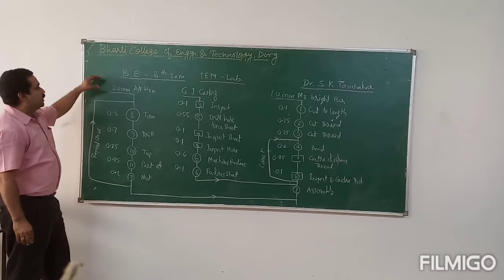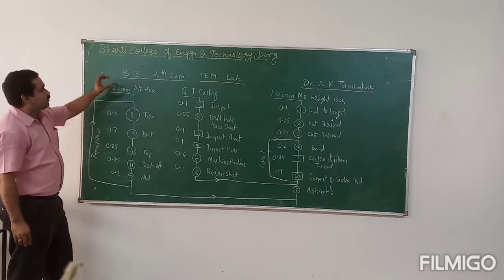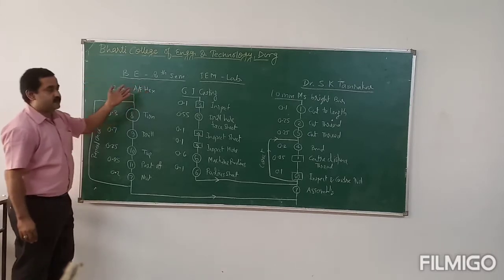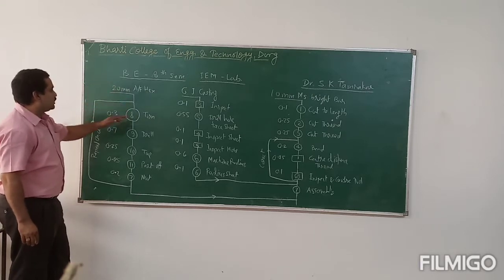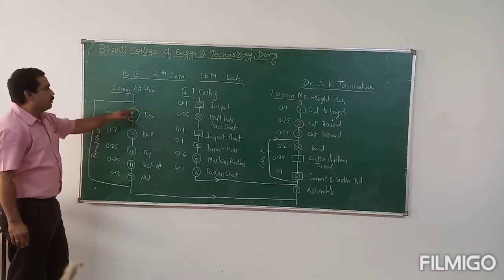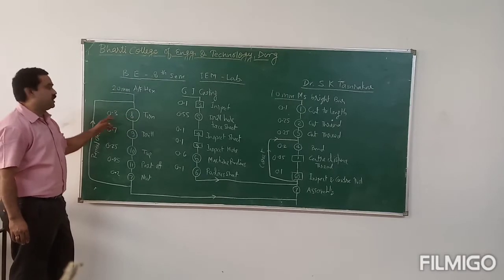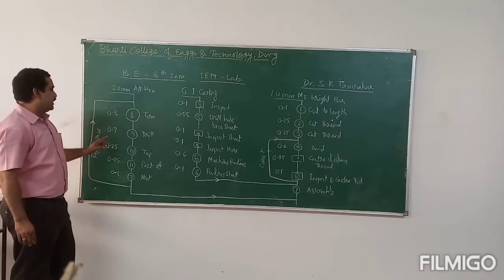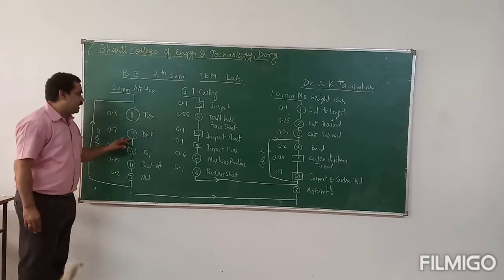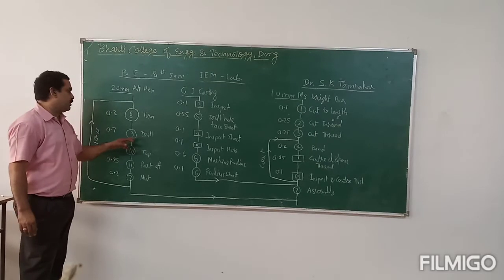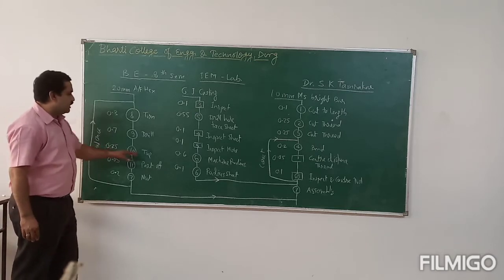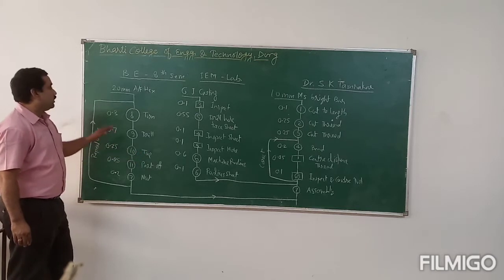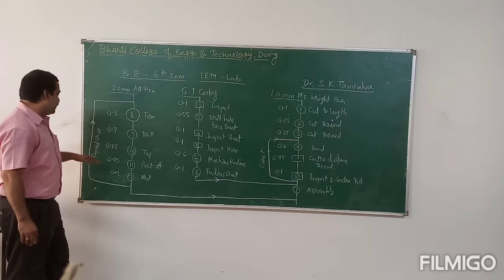On this sheet, the 20 mm AF hexa cutting is done, and then this is the 8th operation, where turning is done, 4.3 seconds. Then drilling is done. This is the 9th operation, 0.7. Then 0.25 tapping is done for the AF hexa.